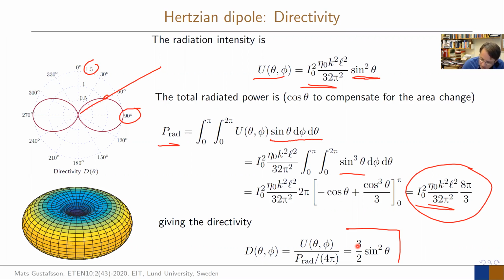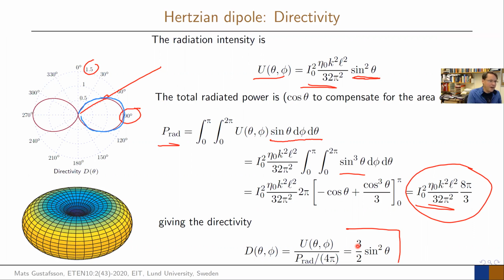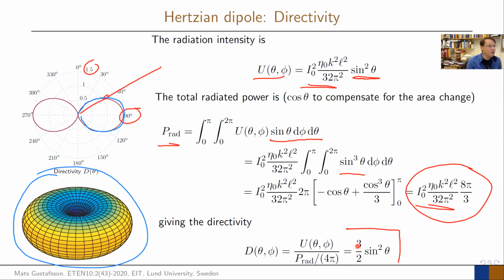And this is how we plot the radiation pattern. We typically plot it in a polar coordinate system. So this is how it looks, and that is the intuition of it. This pattern in this case is independent of phi, and that means we can plot it in a 3D way, and then we rotate this around. And if you're hungry now after lecture, it looks like a donut. So when you think about the radiation pattern for a short dipole, think like a donut. And the maximum value is 1.5. That is given, and that is the smallest electrical source that can radiate.